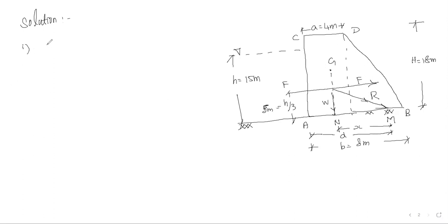So first, the force due to water, that is F. Density into area into H bar. So the formula is nothing but density into H squared by 2.